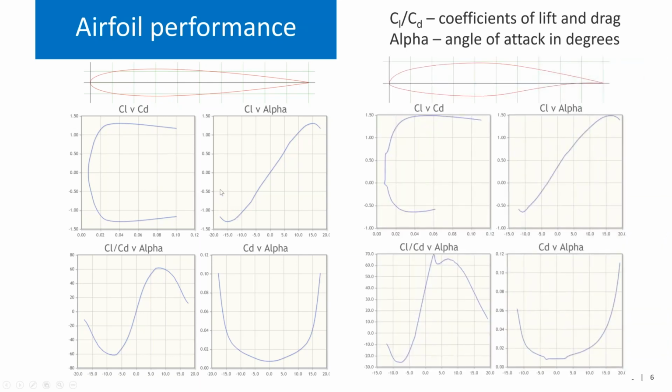For an airfoil that's more shaped like an airfoil that we would commonly use on wind turbines, which is not symmetrical, you will have some lift at zero angle of attack. That's this point here. But the point I want to make with this slide is that all of this is fixed once you fix your airfoil shape. The shape of the CL CD alpha curve is fixed. It's airfoil dependent and not dependent on anything else to first order.